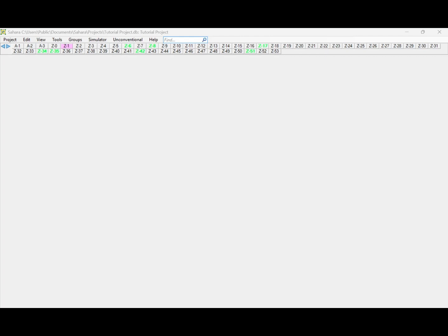To perform the simulation of a water injection project, we always recommend performing some previous reviews in order to validate the input. Your model will be only as good as the input data that you put in. So here are some recommendations, some steps to follow before starting with the simulation. First, verify that all active producers and injectors are in the project.